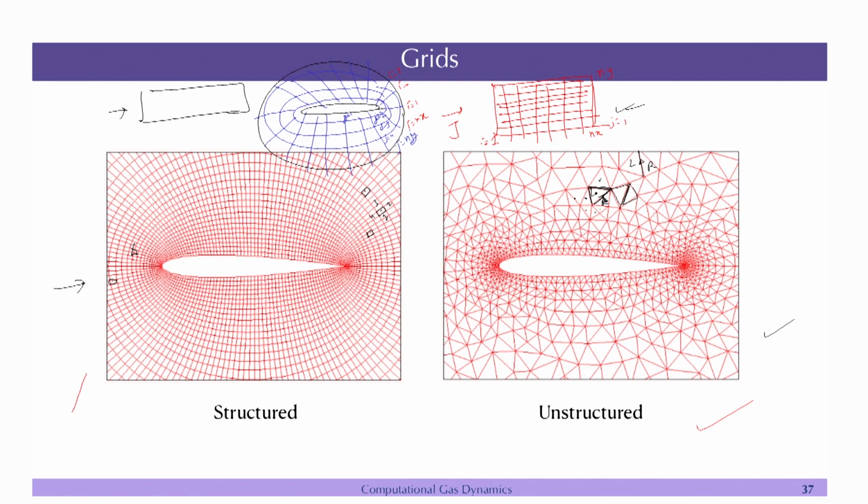In this they are oriented in every single possible direction. You can see that the orientation of each cell is different, and if you go very close to the grid, the connectivity also is very different, right. So, working on this kind of grid requires you to use finite volume, and sometimes finite element can also be employed in this kind of problems. Here you can apply the finite difference or finite volume both.